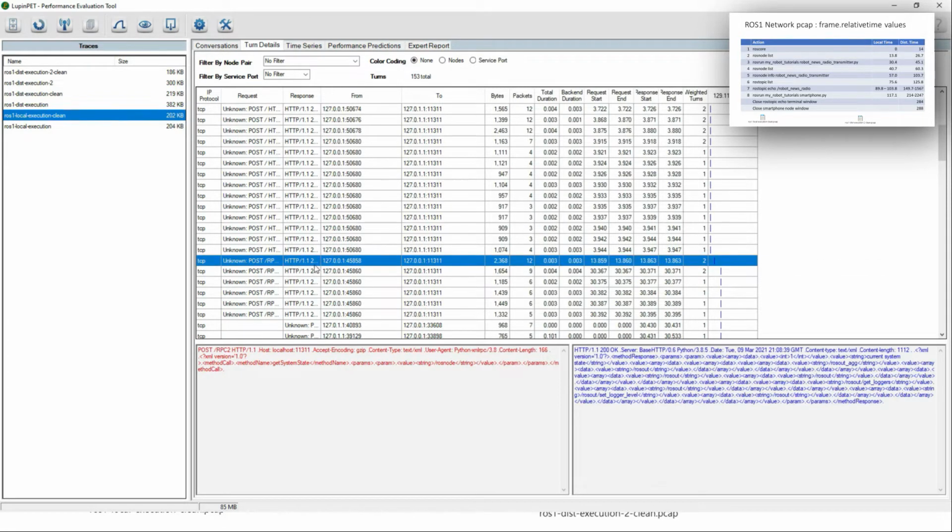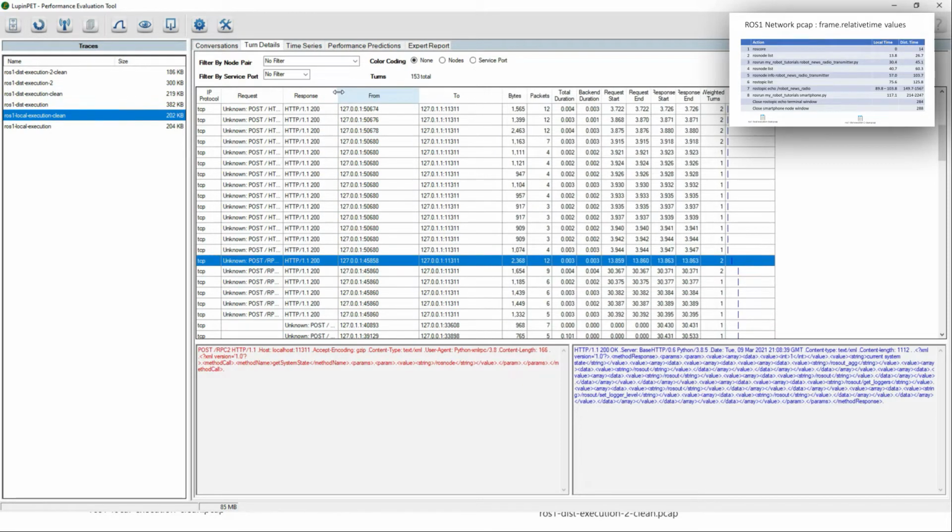going between, let's pull out the addresses here a bit, a port that represents the process that's running the ROS node list command, 45858, and it knows based on the environment setting that the ROS master is local on port 11311, which is standard for the ROS1 ROS master.